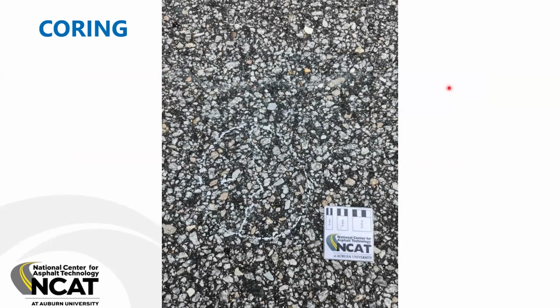And so when you're pulling these cores, if the cracks are still very, very tight, this is still a hairline crack that we're investigating here. We went ahead and marked it on the surface and marked the crack location. And then there's a small arrow there that you can see that is marking our direction of traffic, because of the shear plane, and if we're possibly going to do some bond strength testing, we want to make sure we're shearing those in the proper direction.